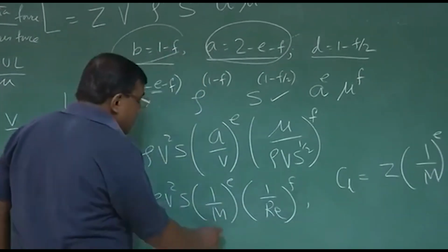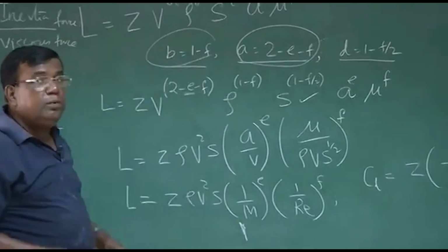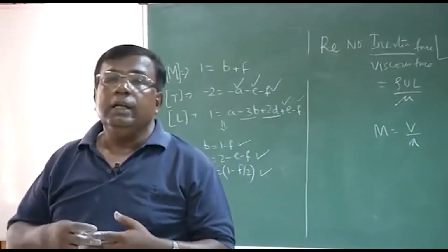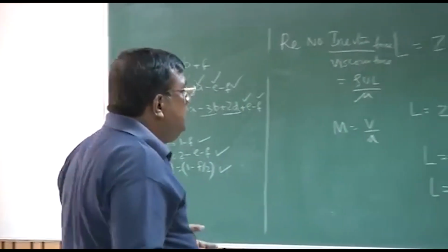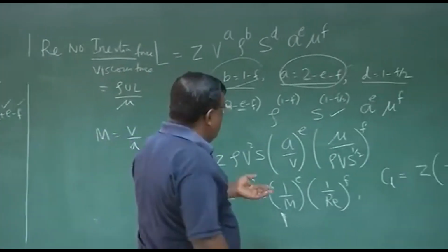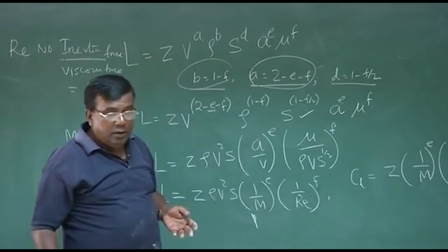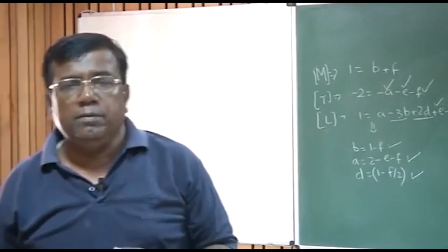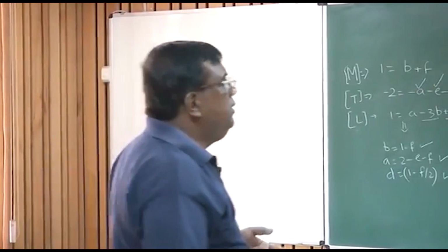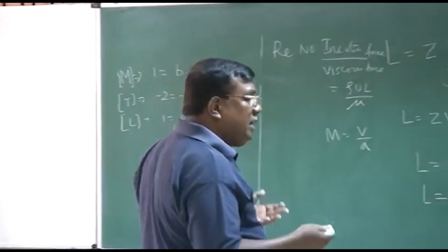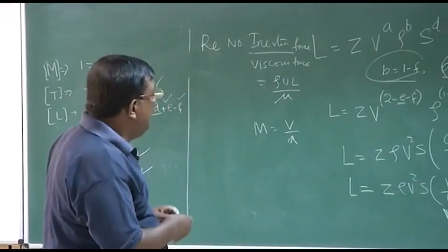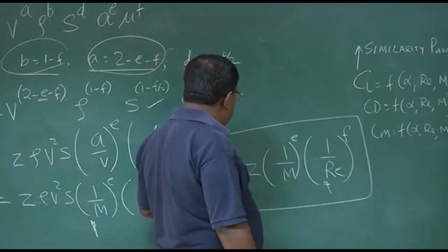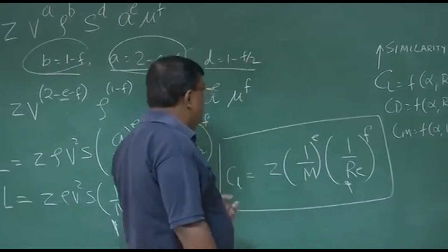This is important for compressible flow when the speed is near Mach 1 to more than 1. Okay? In fact, beyond 0.3, this effect starts playing a role because the flow becomes compressible. For all our lectures in this course, we will be talking about incompressible flow, that is, the speed of the aircraft is low and the Mach number is less than 0.3. Okay? Let us understand what is the advantage, what is the benefit we are having from here.